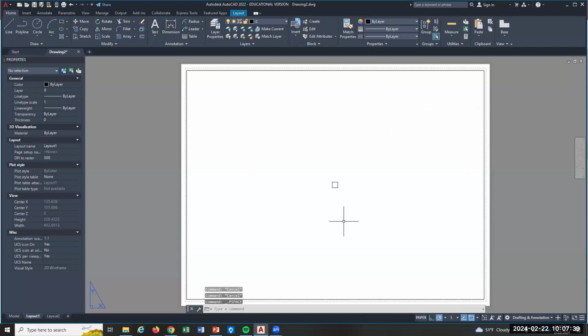Then you'll want to set up your title block. Again, go get your title block from wherever you created it. Go into layout, this view, highlight it all and do Control-C, then bring it in here and do Control-V, and you can bring your title block in. It'll come into the metric template 25 times smaller, because this is metric. You may have to scale it by 25 times. You could just recreate it if you want, but you don't have to.